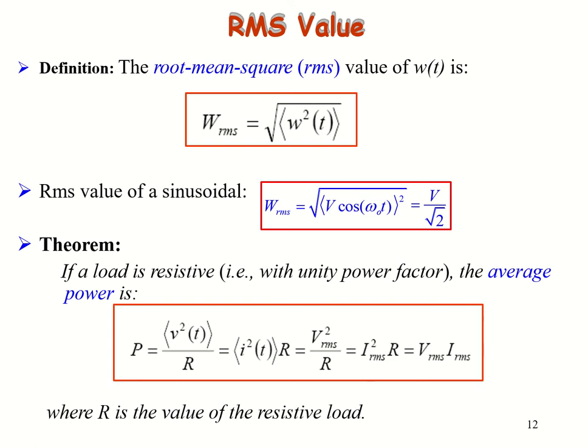RMS value. We get one DC value of a signal, which we represent using this operator. If you take the square of the signal, and take its DC value, and then take the square root of that, that will give us the root mean square value, or RMS value, of a signal.